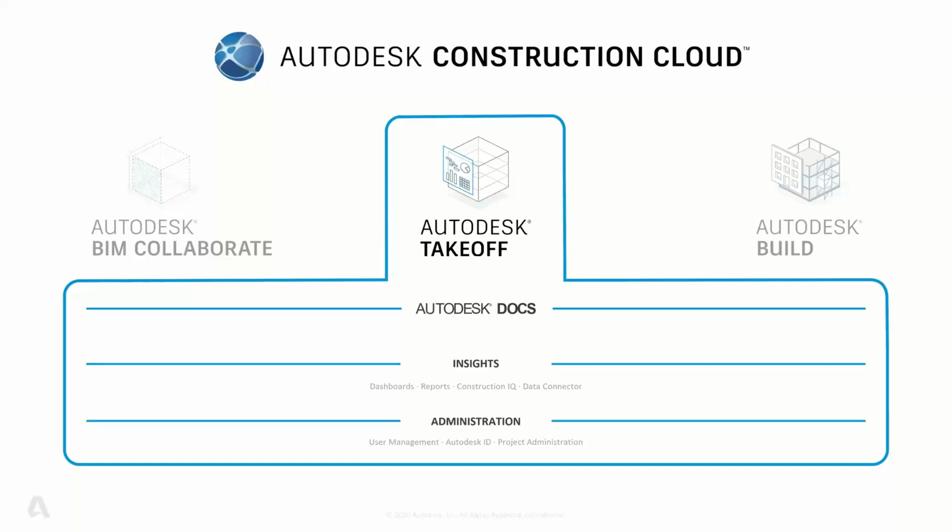And then through that system, we have the ability to compare different models or different views together in order to create clash. And then from there, we can assign issues that then go back to the docs system. So all of that issue tracking is done globally throughout the entire system. So when we pin an issue to an object, if it's a coordination issue like a clash detected between pipe and structure, we can pin that to the model, issue it to an individual with a deadline, and that gets put back into that system that Scott was showing with issues, and we can manage it through there. I think that's essentially what we were going to show from BIM Collaborate.